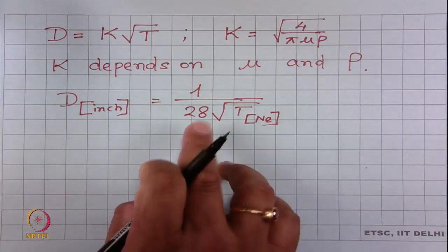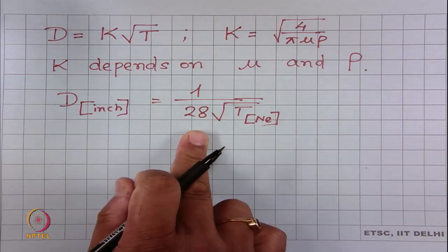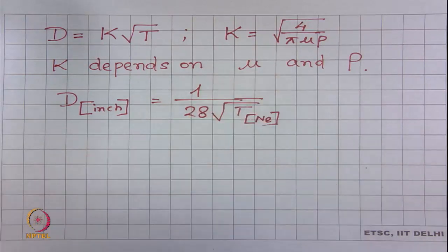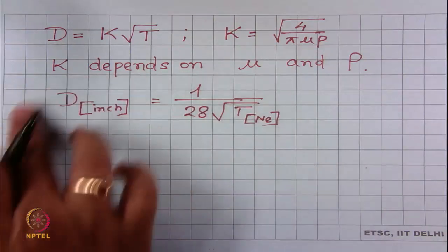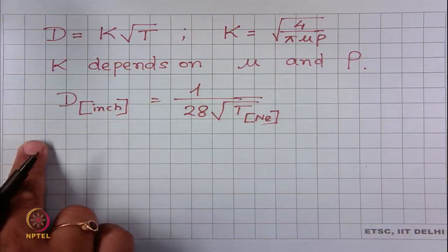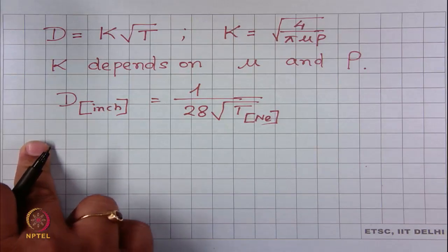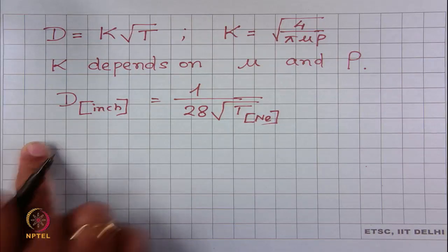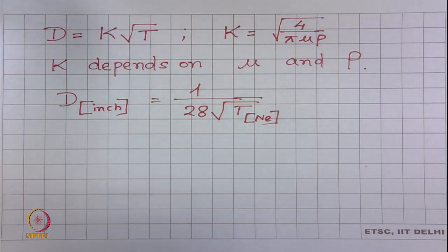It cannot be applied for all yarns, even if they are prepared by using same fibers, because packing density is not constant. As packing density is variable, this relationship is not true for all yarns, even if they are prepared by using same fibers. This is a very popular error that we commit.